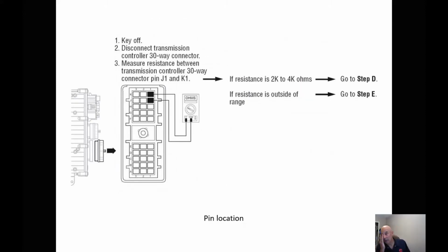Some of the new things that they have because of computers is, let's just say for instance, I've got my lockers in. Over a certain speed, the engine and transmission ECMs determine that we're going too fast for lockers, and it will disengage them. Our PTO on our transmission, we can't start a vehicle if the PTO is engaged. So customer calls and says, yeah, I can't start my truck. Make sure the PTO is disengaged if they have one. It could be the clutch pedal switch has failed.